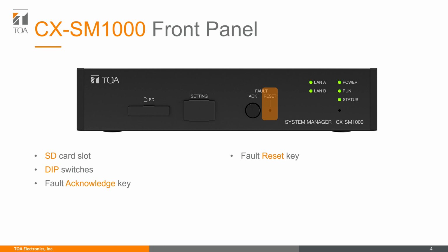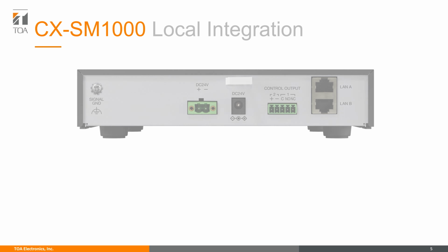On the right, you'll find your status LEDs, and below that is the device reset, which is executed the exact same way as the fault reset. Once again, use a small object about the size of a paperclip, which will press the button and restart the device.